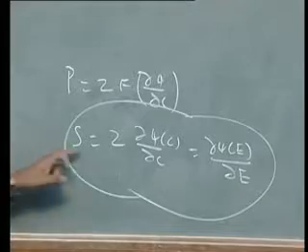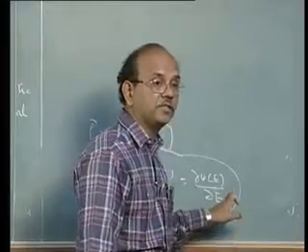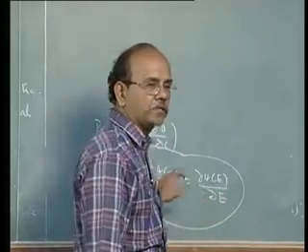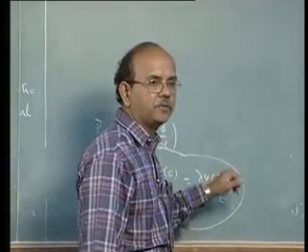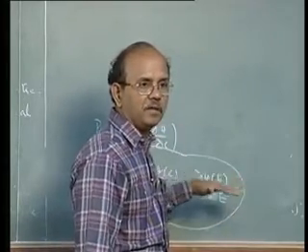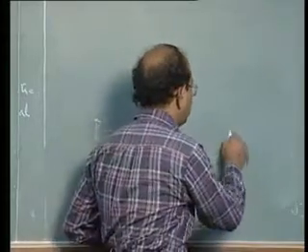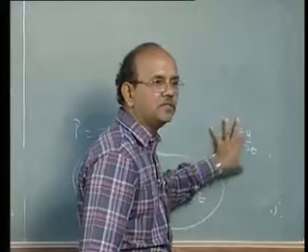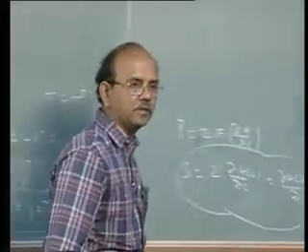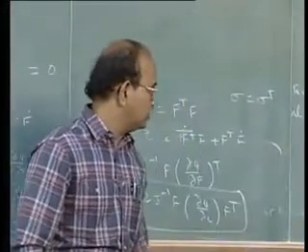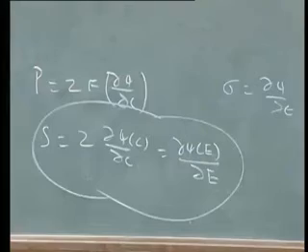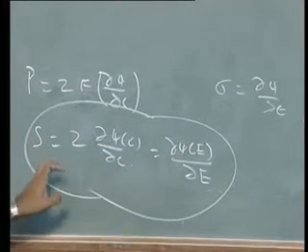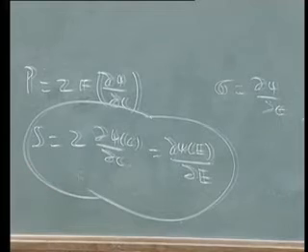So S is equal to, if I express the strain energy density function in terms of E, then dou psi by dou E. If you remember, we had approximated S to be sigma and E to be epsilon, and in fact, in the last course, we had just said sigma is equal to dou psi by dou epsilon of the strain energy function, because of the small deformation case that was involved there. So you get that important relationship between the strain energy density function and the second Piola-Kirchhoff stress.